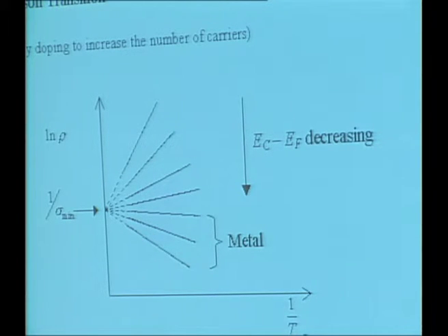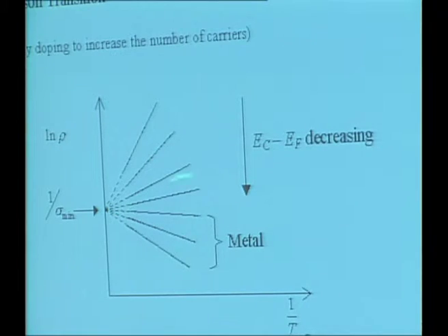Okay? If the mobility edge is such that the Fermi level is in localized states, then you must do thermal activation from the Fermi level up to the mobility edge in order to get electrons to move. Okay? So as the mobility edge moves toward the Fermi level, these slopes get less and less. Finally, it becomes a metal, and then you get metallic-like resistivity.